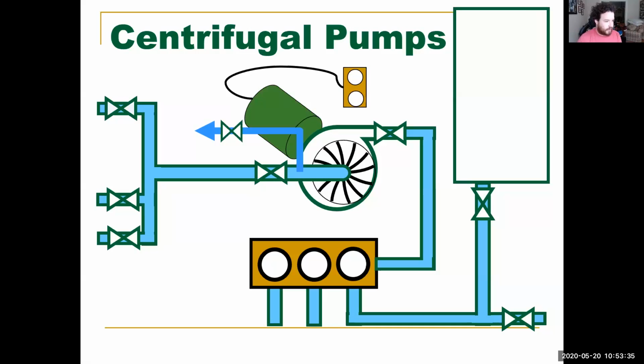So let's continue on with a centrifugal pump. So first thing that we have to do is determine which tank we're going to come from. So we're going to be opening up our suction. There we go. So our suction is being opened. This is our tank that we want to come from. Our suction is opened. Wherever that goes, I don't care, but it's closed. We go into a manifold. All right. That manifold has a valve right here that we're going to be opening, and it's going to be sending it to our pump. As I did this all backwards.